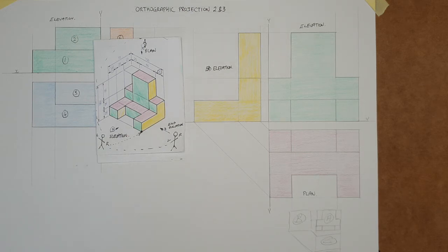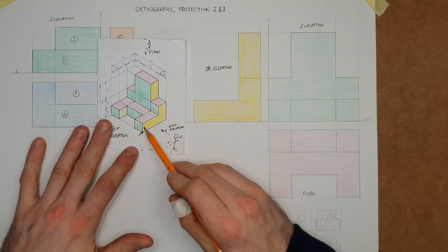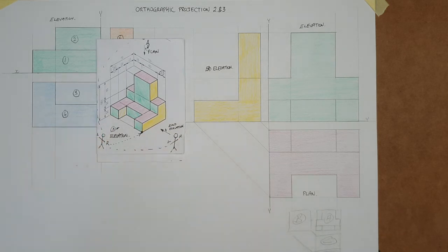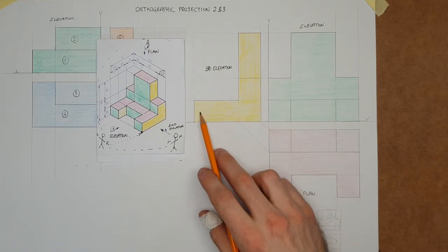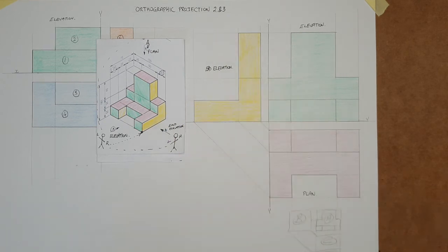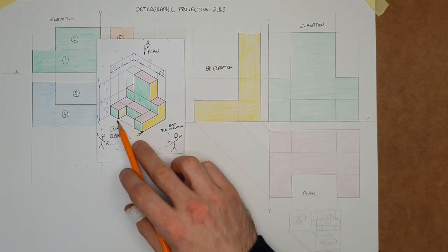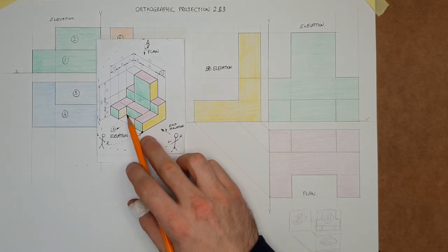There's a way that we can represent something like that. So something that is present, but maybe it's not present on this surface, but it's happening at the back of the object. Well, if we wanted to give these drawings to somebody and show them everything we possibly can, then there's something missing here. We're saying to them, that's it, there's the yellow surface, we can see nothing else. Well, I'd like to show that there is something happening here, where it steps in by 25 mm.